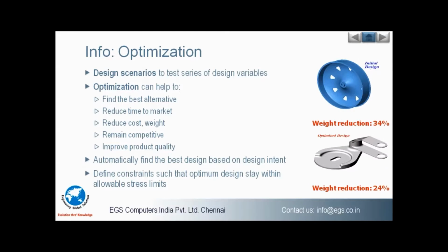And you can even directly link all the study result outputs to the optimization. Say we were discussing the frequency analysis, even the mode shapes can directly be linked to the optimization study. Or if you are going to calculate the life from the fatigue analysis, the minimum life cycle of the product can also be taken as a goal to directly evaluate the product performance.